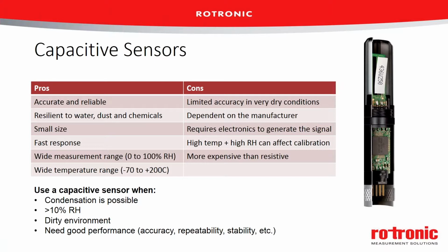Often I say the best sensor for contamination is our own nose. If you can smell something in the environment, there's potentially something there that to the RH sensor could be a contamination. So if you're seeing sensor drift, that's quite often the cause of it. So it could be looking at what's actually there and then perhaps choosing a different capacitive sensor.